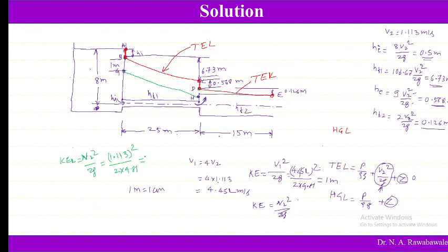So this works out as 0.063 meters. So from point D we are going to subtract 0.06, which is less than 1 mm. So here we are going to get one more point, I, by reducing this distance of 0.063 meter. And again from point E also we are going to reduce 0.063 meter, which is 0.6 mm, approximately 1 mm. Then we get this hydraulic gradient line, H.G.L.